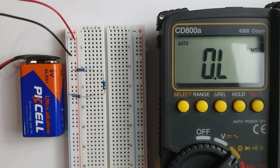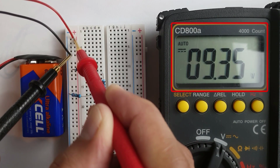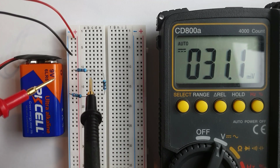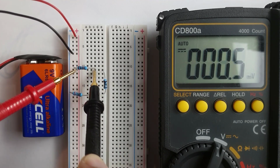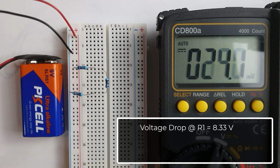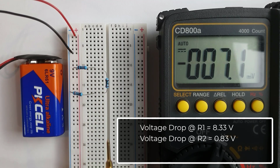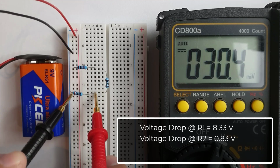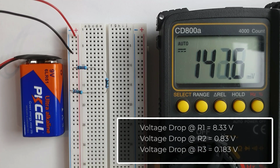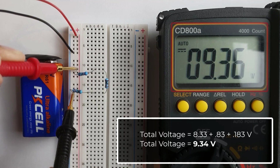For this example, this battery as our voltage source, when measured using a voltmeter, has a value of 9.35 volts. So if I measure these individual voltages across each resistor, like in this 10 kilo ohm resistor, the voltage drop is 8.33 volts. In the 1 kilo ohm resistor, the voltage drop is 0.83 volts or 830 millivolts. And for this 220 ohm resistor, the voltage drop is 183.2 millivolts. Now, if we add these three individual voltages, the total is 9.35 volts, which is equal to the total supplied voltage of this battery.